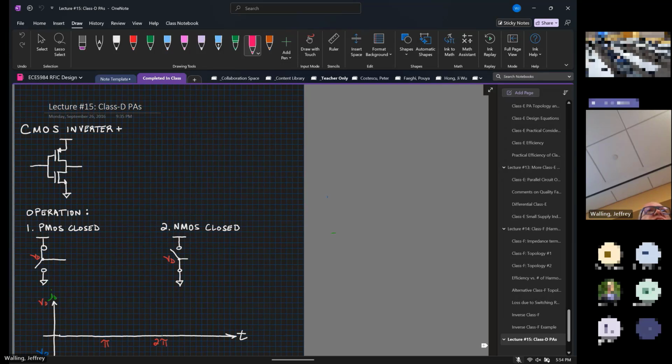If we made that filter instead of series resonant a low pass filter, that would be what people in the analog or in the power electronics world might call a class S amplifier. And then class D in the audio amplifier world would be a low pass filter instead of a band pass filter. So the names do get mixed up across the different circuit domains.